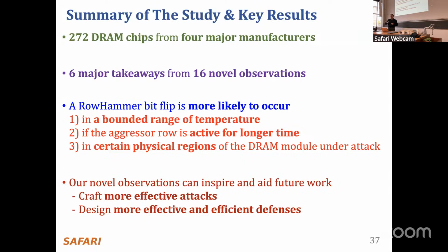Retention errors are a very well-known charge leakage mechanism, and charge leakage accelerates significantly with temperature. It's actually an exponential relationship, right? Okay, so this makes life a bit harder for testing, as you can see.